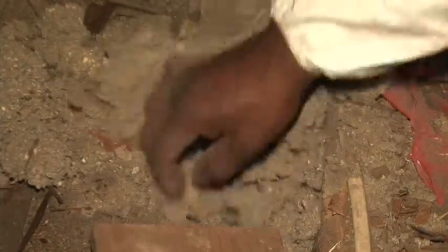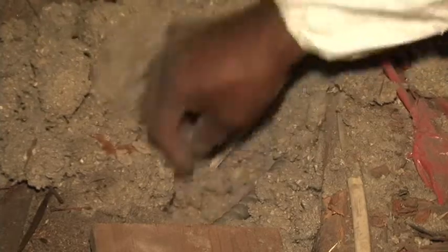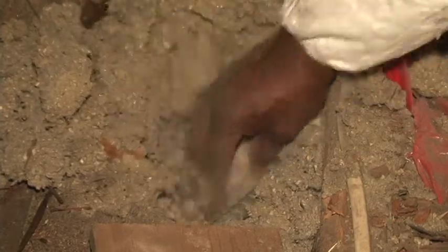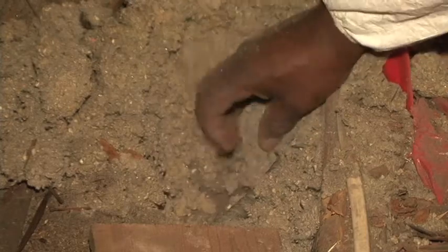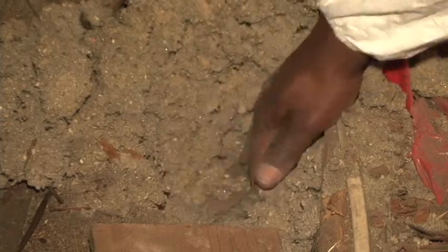Okay, so I'm checking for the air barrier, so I'm digging down through the insulation here until I get to the ceiling. There's the ceiling, and there is no air barrier here. And you might be wondering what this red plastic is. Likely it's simply the bags that this original cellulose came in, and really doesn't mean anything. Next, we look for any signs of air leakage from the conditioned space of the house into the attic.